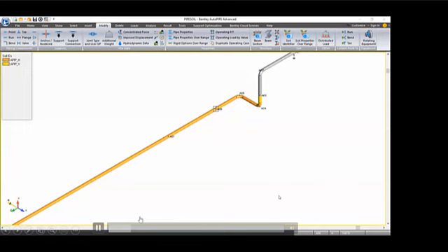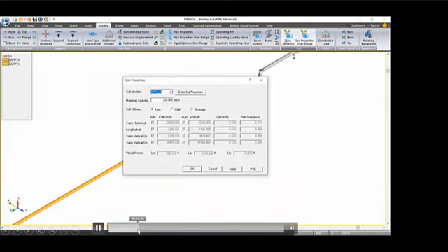And when you are defining this, you need to define a soil property, okay? The soil property, you can modify or create and insert or modify, but works, a soil identifier. So the identifier could have the name you consider. It's a name, okay? I can put Carlos if I want, okay?